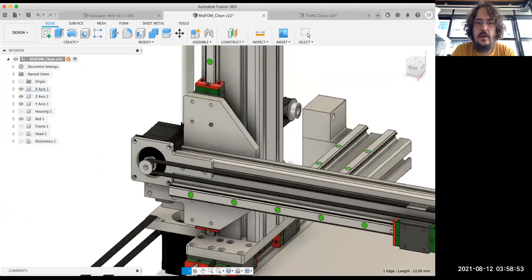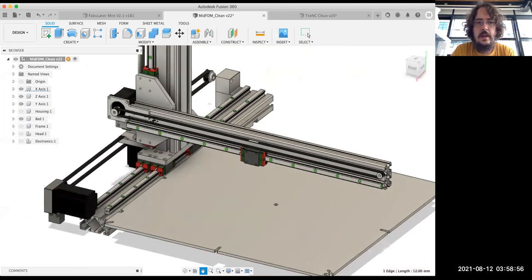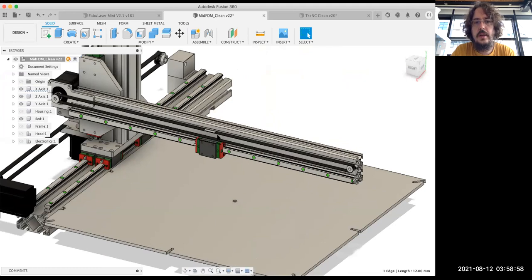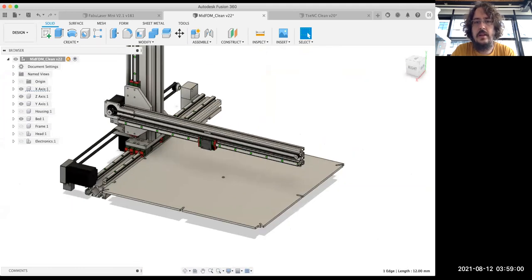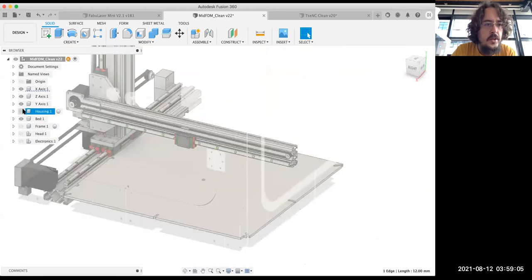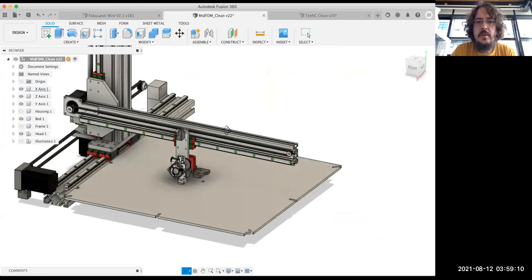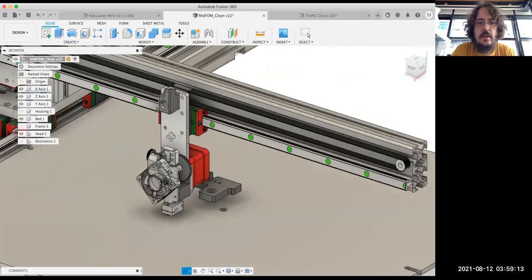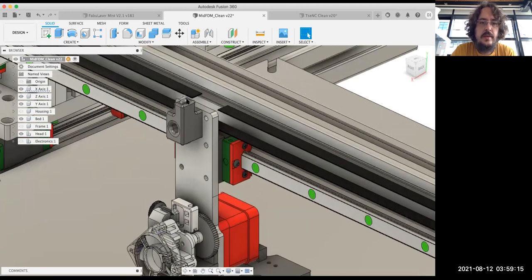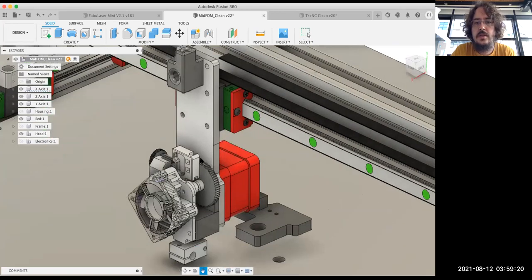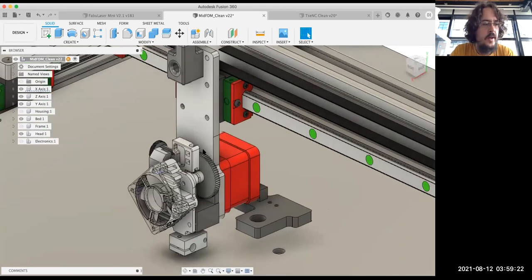And then this employs another aluminum profile, and then another NEMA 23 motor, and a belt, and then a linear guide again of the same kind. And then here there will be the head of the machine printing. So the machine is very simple. It has a filament hole here where the filament is going to be directed to the extruder. For the extruder, we have an E3D Titan extruder, and then here we have a holder for the sensors.